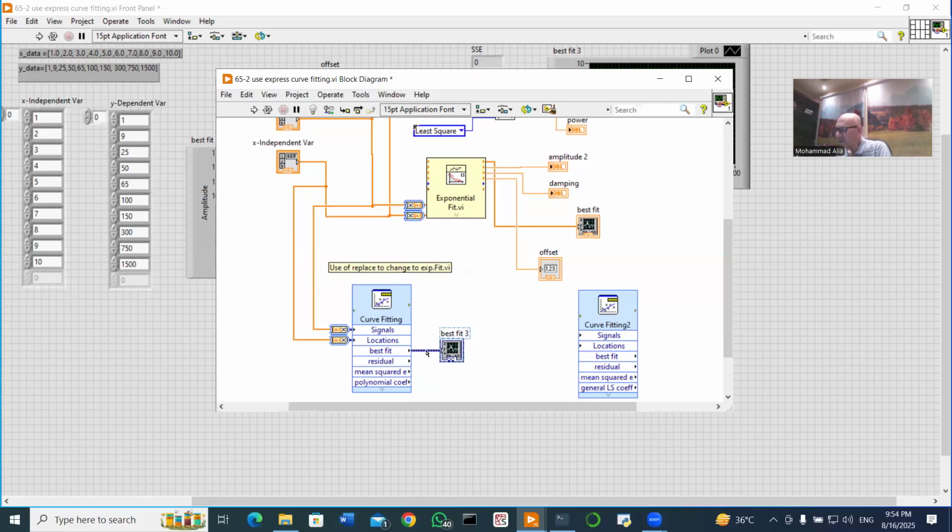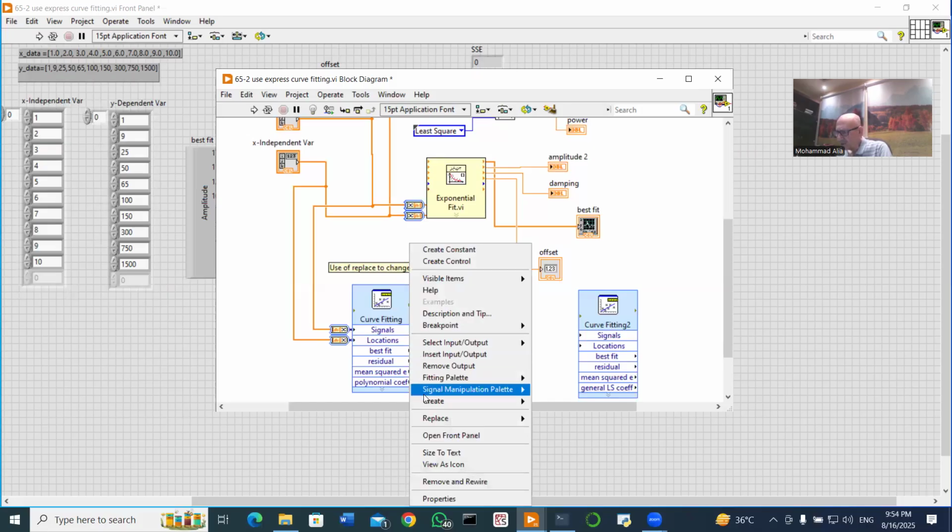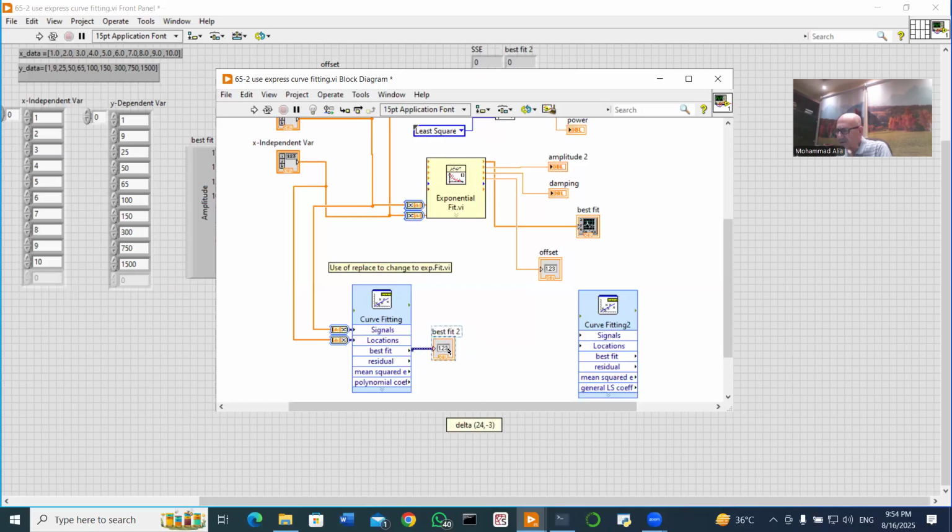If you want to have numeric indicator values, as I expect, it should be an array. So let me take this away. Now I again right-click here and go to create a numeric value. Here it is given as the last value and not as an array. This is a value, this is not an array, so I have taken this away, I don't need it.